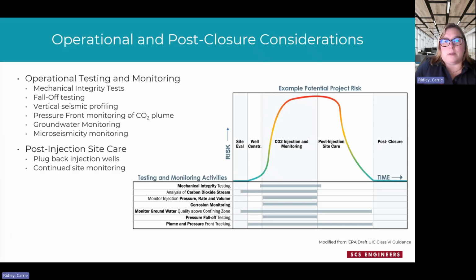So once a project becomes operational, there's ongoing monitoring and testing that gets reported to a regulator quarterly, up to annually, depending on the type of reports. Overall, many things such as injection rate and pressures are monitored with SCADA systems with 24/7 monitoring. Many wells have instrumentation downhole to monitor any microseismic activity and pressure changes related to the volume of injection. Models are constantly refined and compared to the facility performance to reduce risks and unknowns related to the failure in the system.